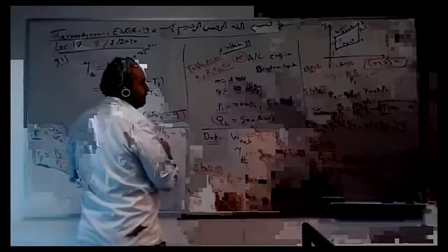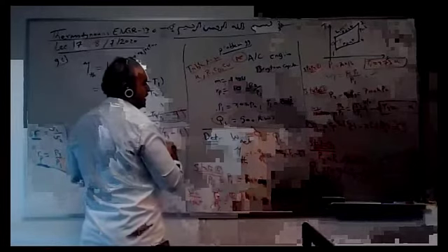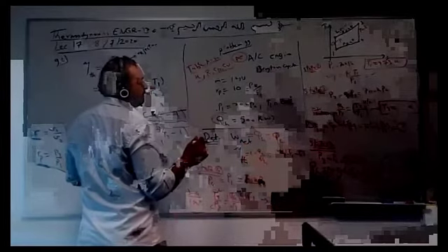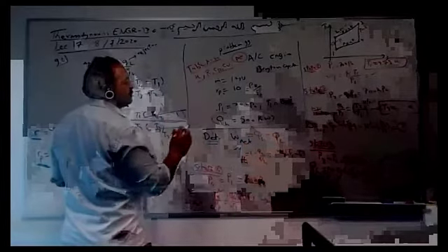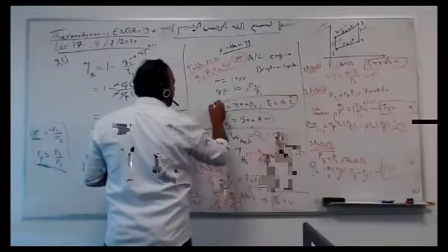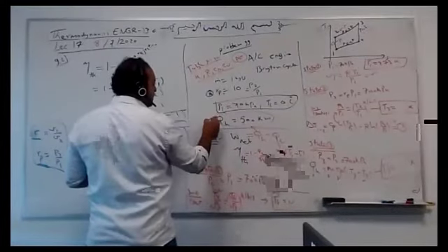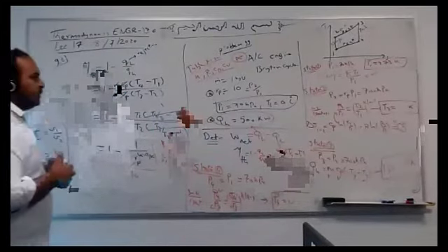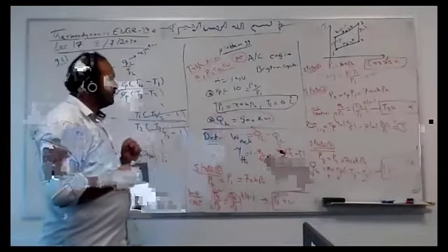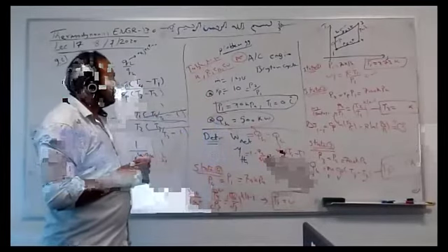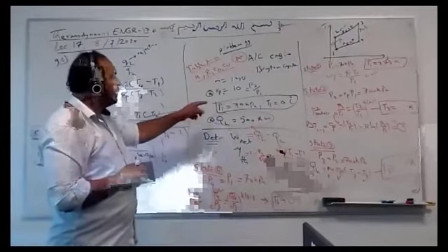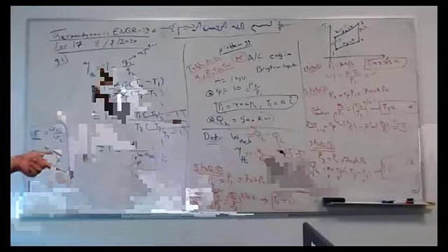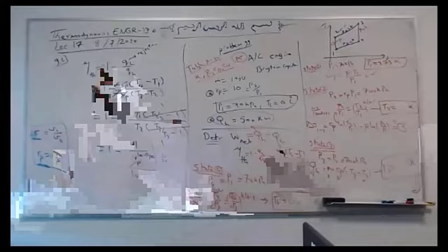Inputs, you can get everything. I can replace this by T3. I can replace, for example, this by T2 and T3. So I give 4 pieces of information, usually state 1 and 2 other things. With the pressure ratio, you can get everything in the cycle. Actually, with only the pressure ratio or compression ratio and cutoff ratio, you can get the thermal efficiency for Brayton, Otto, and diesel cycle respectively.